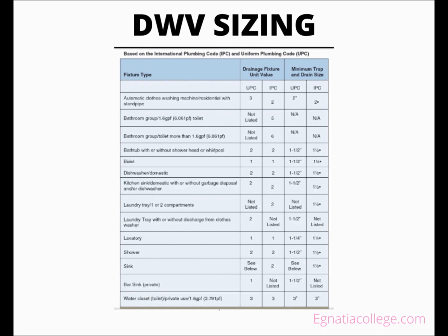Theoretical methods that determine sizing are based on the rate of flow at which a fixture discharges wastewater into a drainage system. The measuring factor is a DFU. The average plumber does not perform calculations on a job site, but instead uses the known DFU values of fixtures to locate correct sizing information in a code book. Most DFU values listed in a code book are based on the flow rates of certain fixtures, pipe sizes, and the DFU load effects on a DWV system.